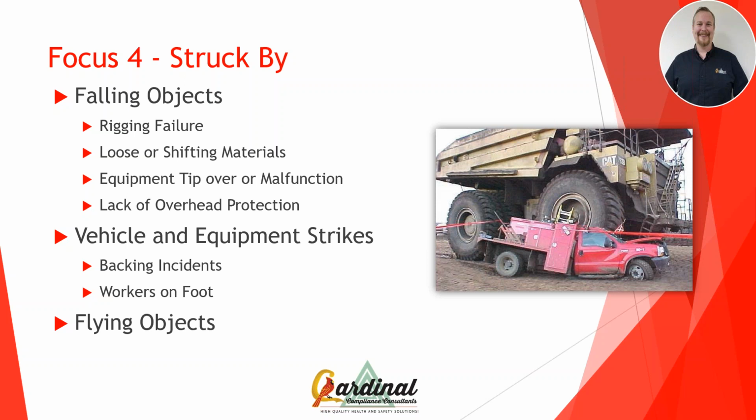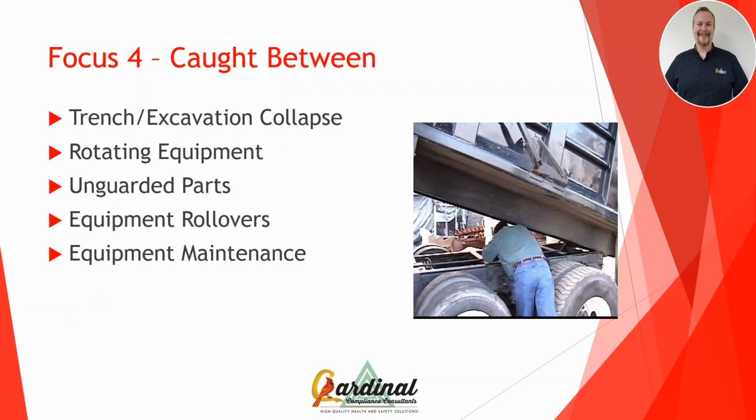And these are some of the things you need to look at: the higher up your building, the more potential that you have that something's going to fall. And what's amazing is it seems like no matter how hard you try, that wrench, that power drill, that socket set, it's amazing how quickly they can fall. And so that's why you need to make sure you put some netting on your scaffolding. That decreases the chance something can fall between your mid rail and top rail.